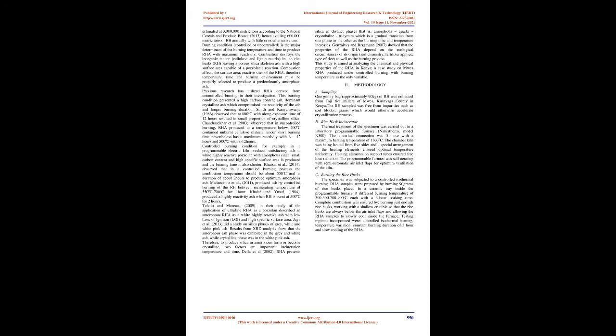Combustion affects the surface area and reactive sites of the RHA, therefore temperature, time, and burning environment must be properly selected to produce a predominantly amorphous ash. Previous research has utilized RHA derived from uncontrolled burning in their investigations. This burning condition presented a high carbon content ash, dominantly crystalline, which compromised the reactivity of the ash and